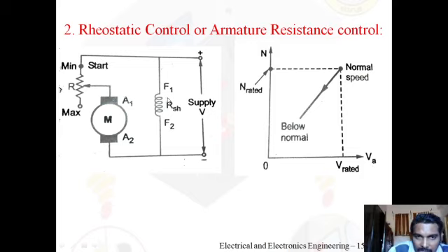If you recall the speed current characteristics, you will come to know that a DC shunt motor is a constant speed motor, right? Now, if you come to the armature part, we are trying to vary the armature resistance by connecting a rheostat in series with the armature.